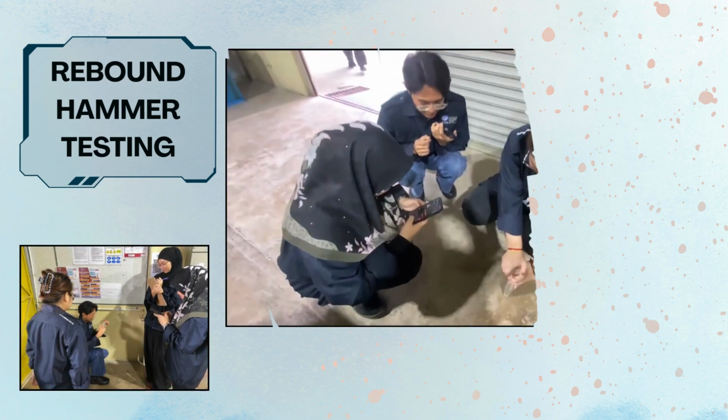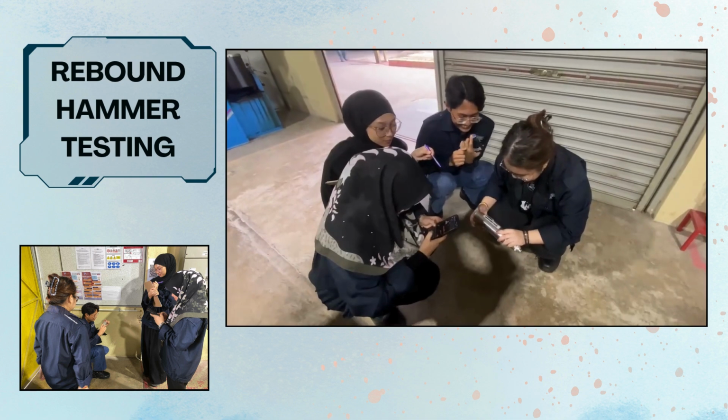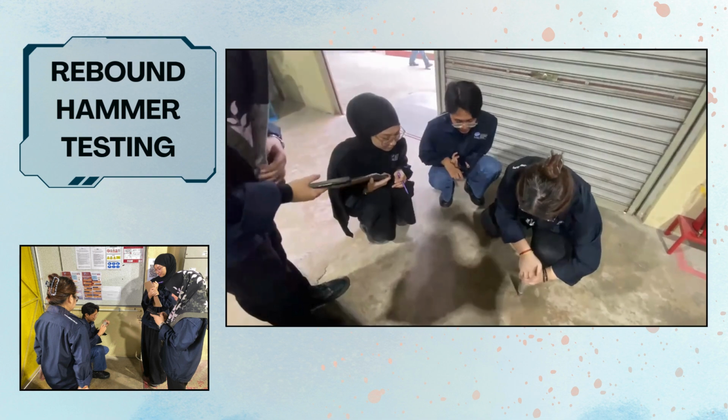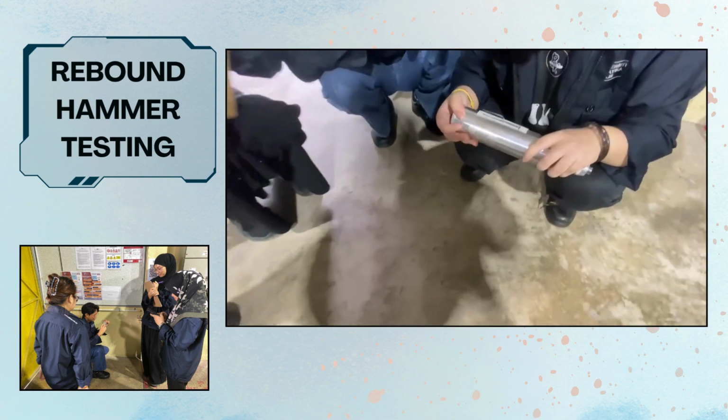First test is the rebound hammer test. It helps us quickly estimate how strong the concrete is. You can see in the picture how it's done. A special hammer hits the concrete and we measure how far it bounces back. A higher bounce means stronger concrete.